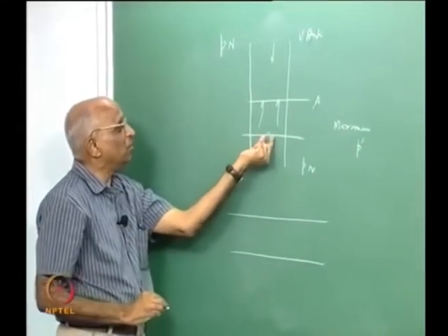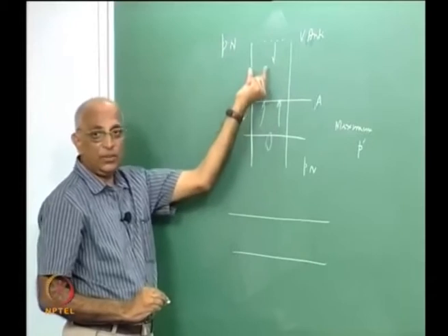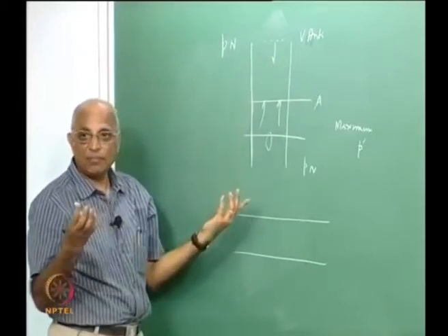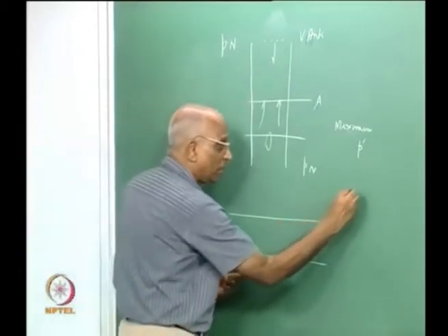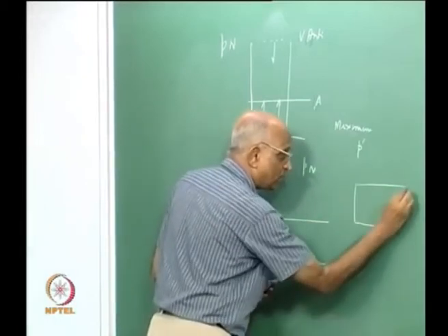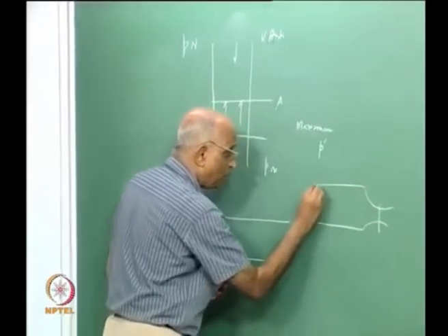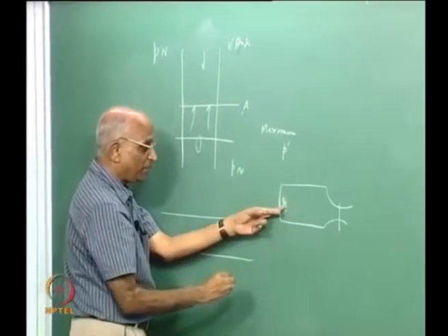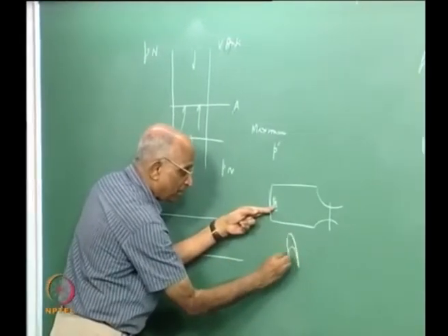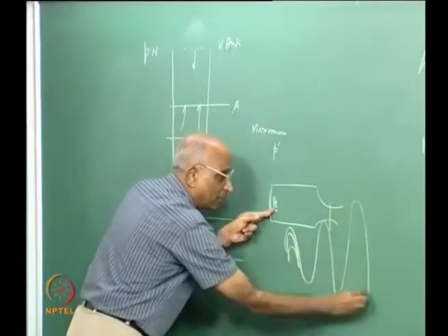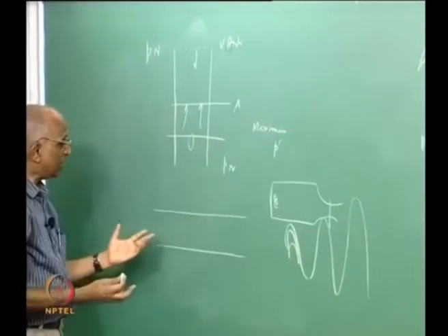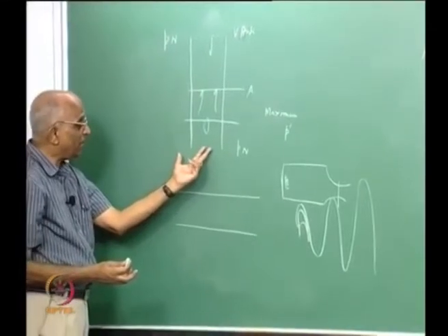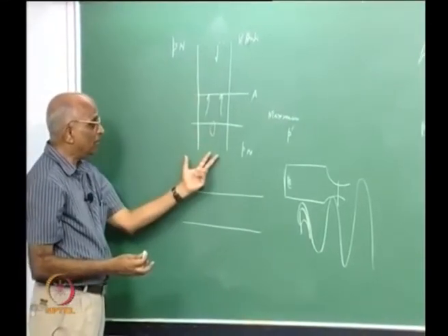Therefore, putting a heat source has caused the pressure magnitudes to jump up, and that is what happens in a rocket chamber. What happens in a rocket chamber? You have the gas flow, I have pressure antinode, pressure node here. Supposing I put a heat source at the location of maximum pressure, well, my pressure amplitude keeps increasing and my amplitude goes up. And this is precisely the principle. In this case it is convective. I had an open tube to do a simple experiment.